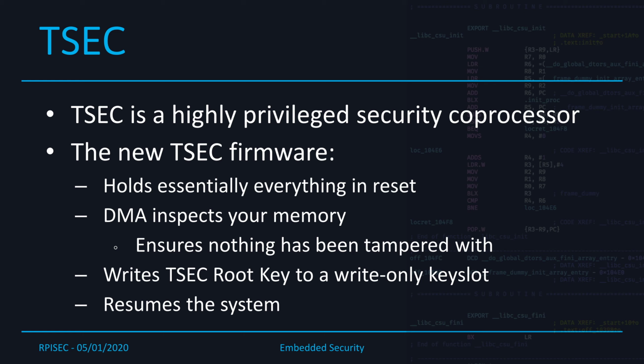So as you boot the system up, after the boot ROM on the boot and power management processor, the actual bootloaders that Nintendo wrote, which you now have to follow if you want the key, are going to upload the TSEC firmware into the TSEC if it's not already running the new updated version, and then it's going to suspend the whole platform.